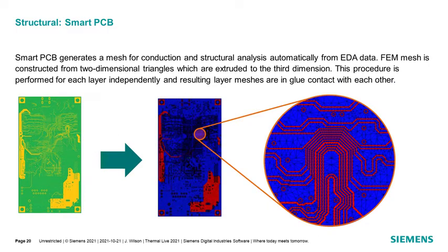The material map allows a really robust and easy method to mesh the PCB in FloEFD. So it's not only easy, but it's very accurate because it's really based on that kind of nodal representation of the fine detail. And just a little bit more in depth, the mesh is two-dimensional triangles which are extruded in the third dimension, commonly known as a triangular prism cell.